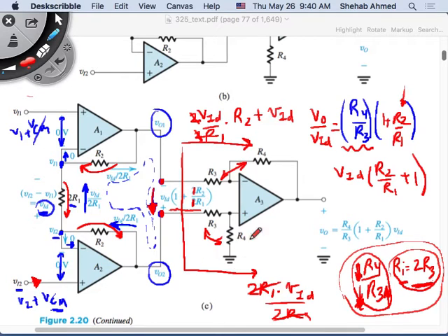So this difference amplifier had two problems: the common mode and R input. The previous circuit and this circuit solved R input easily, and this configuration, after we removed the connection, solved the common mode signal issue, which gave us relaxation on the use of R3 and R4 that are not so well trimmed and tuned to each other.